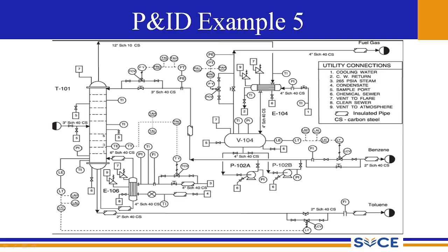So this is how you have to differentiate those connectors, and you have to understand the process flow based on these connectors, and where it is present in the second flow sheet or the subsequent flow sheet. So always remember, you should comprehend the information by using this legend and also the various symbols along with the alphabets, what they actually represent, which flow variable they represent, whether it is temperature, flow, pressure or flow rate. Those need to be properly identified by these alphabets.